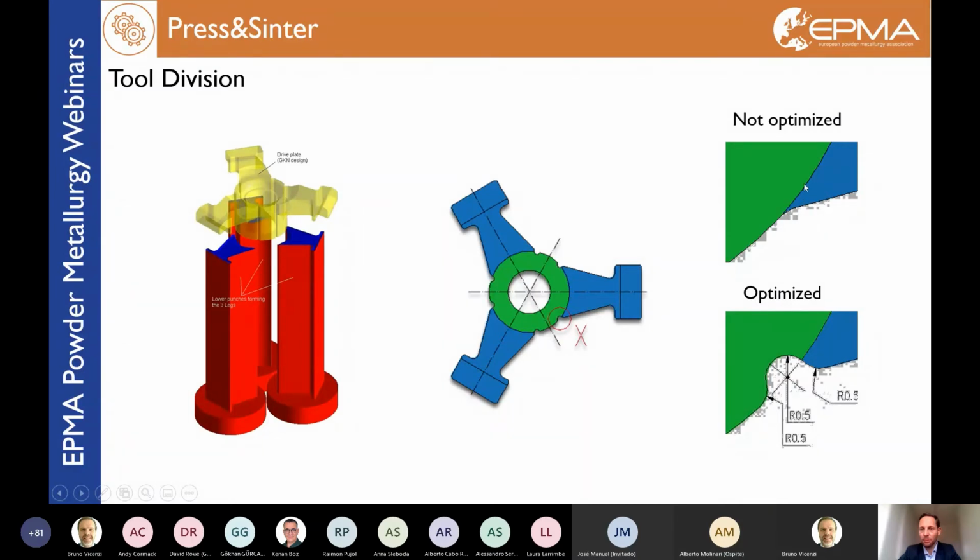This would immediately break down. So the engineer convinced to optimize this blue punch to this geometry. I have here an angle of about 90 degree. 90 degree or bigger is always good. So the tool is not breaking. Tools, if you consider, are made from very hard materials.